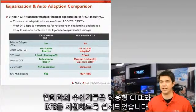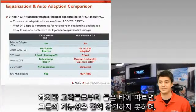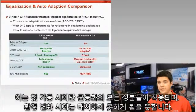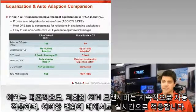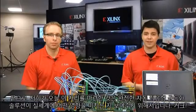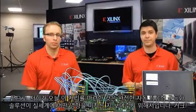Altera's receivers are designed to support adaptive CTLE and DFE. However, we've heard from customers that their functionality is far from robust and that they're recommending not to use continuous adapt mode, but rather a one-time adaptation. This means that only at startup do all of the components of the equalization adapt, leaving any changes to the environment to be unaccounted for. To contrast, our GTH transceiver is continually auto-adapting, adapting to any changes in real time. And finally, this is why we're here today, to show you the real-world impact of a fully auto-adapting equalization solution.